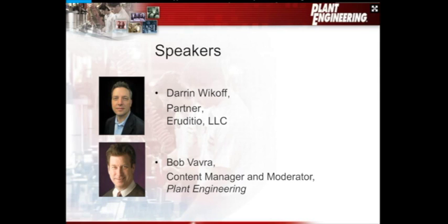So I was talking about the layers earlier, and I said that initially getting started, you're going to evaluate criticality at the system level, and then within the more significant system or systems, you're going to drill down to the machine level. This is where bad actor analysis, or that basic Pareto or histogram analysis, is really good to help me say, okay, these are the top 20% most significant machines within those significant systems.